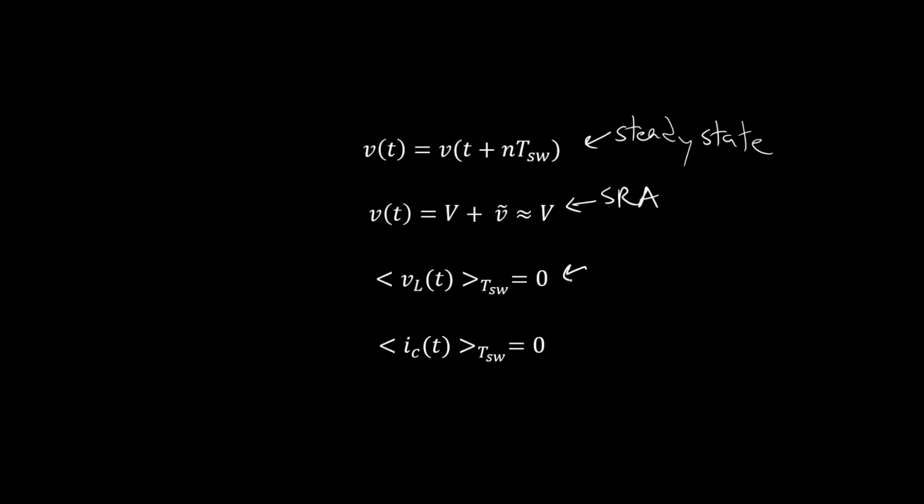We also looked at IVSB, inductor volt-second balance, which says that the average volt-seconds applied to an inductor over a switching period is equal to 0. So if you apply some positive voltage for some period of time, you have to apply a negative voltage for a proportionally large amount of time. So IVSB: the volt-seconds applied to an inductor in one switching cycle is 0 when you're operating in steady state. So these both assume steady state operation.